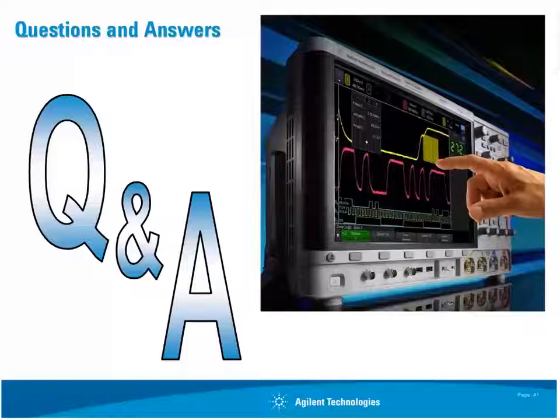Okay, thank you. Next question. What can I do on a scope to maximize update rate or reduce dead time? Well, a lot of scopes have trade-offs. If you look at different vendors' oscilloscopes data sheets, their specifications, they all, including Agilent, will highlight the best case. There's a lot of factors in a scope that are going to affect waveform update rate.